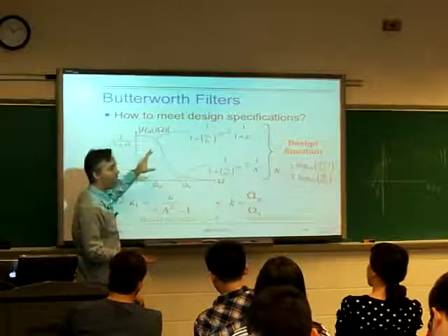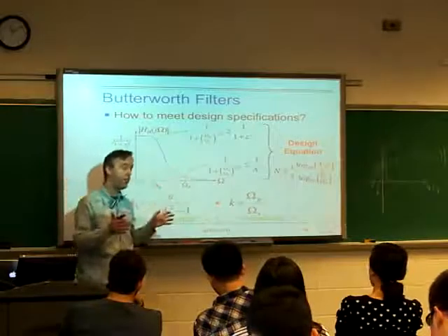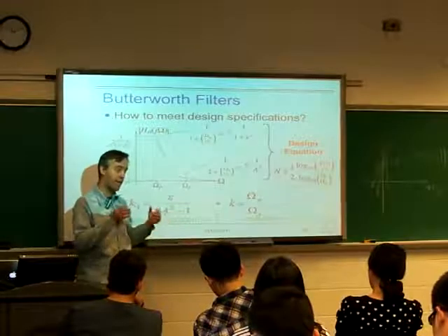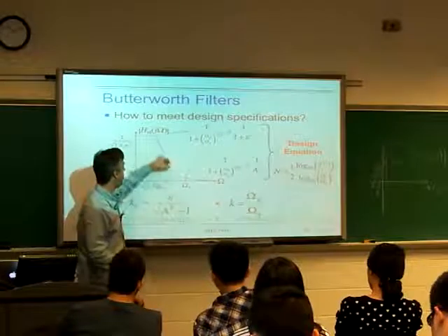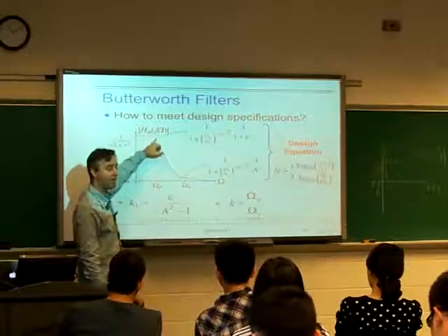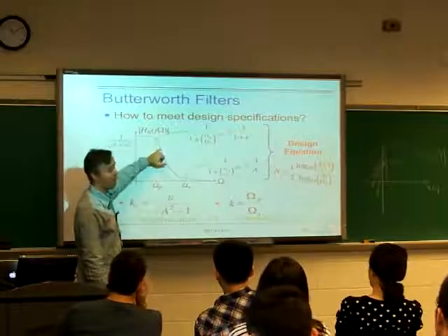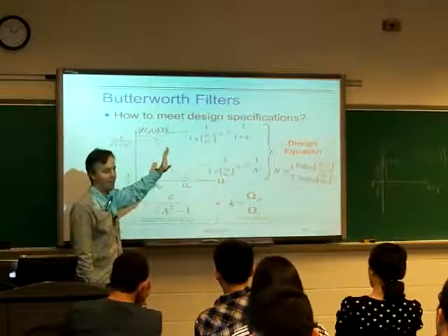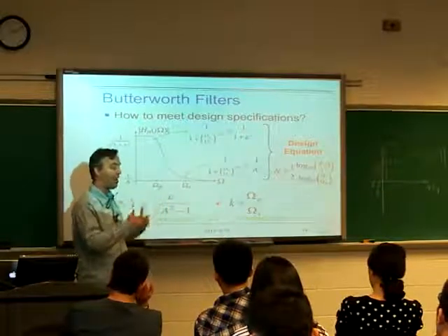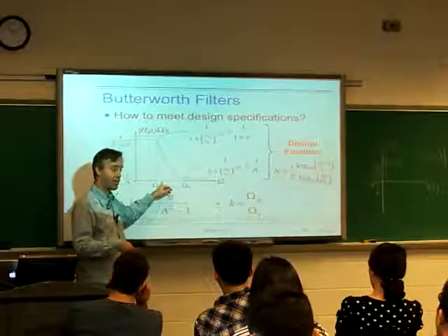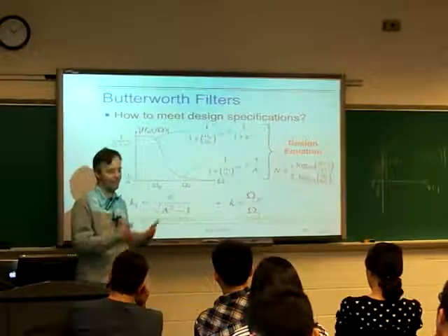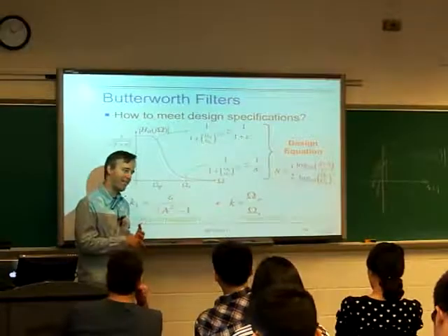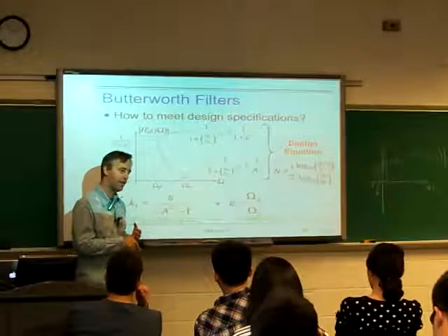It's like, well, yeah, but I can't deal with 3 dB attenuation in my passband. My passband's got to be within half a dB. So then you back up the curve to that point. So now we're talking about this point, but if it was 3 dB, then we'd be easy. The actual passband edge I care about is the 3 dB point, so I don't even have to normalize that out. It's already there. So omega p is where exactly my first transition starts.